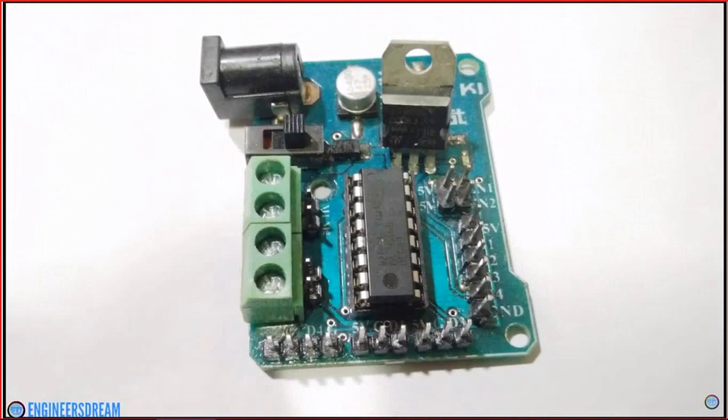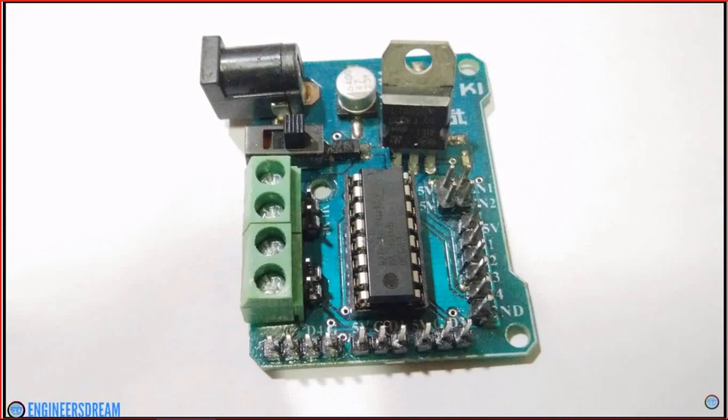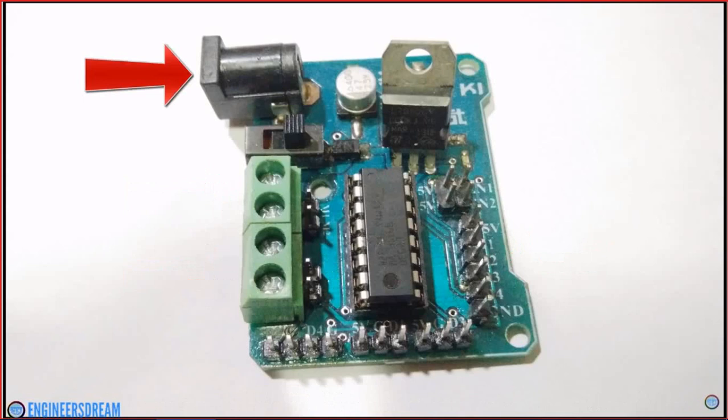And if you look at the last motor driver, then this motor driver is more advanced than the other 2 motor drivers. It consists of D1, D2, D3 and D4 pins which are connected to the input pins of the L293D IC. And as you guys would have guessed, these pins will be connected to the Arduino's data pins. The DC motors will be connected to the green sockets which are labeled as M1, M2, M3 and M4. And I had to connect a battery to the DC jack connector for providing power. The breakout board also consists of an on-off switch using which I can switch on and switch off this board.